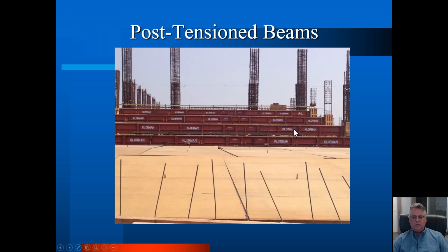These are steel beam forms. So in long span post-tension concrete, the beam forms are usually steel, and the slab forms are usually plywood. So you'll see that indentation from below with the plywood, and a nice clean look on the steel beams. Be careful. If you stand still too long on one of Bill's jobs, you may get spray painted with his name. So try to move around a little bit when we're on his projects.